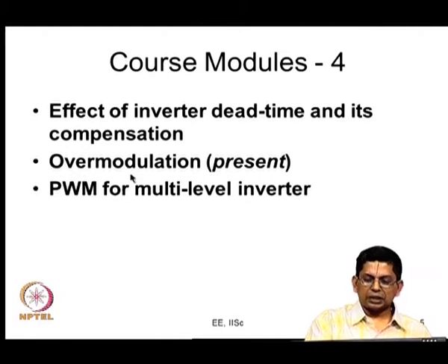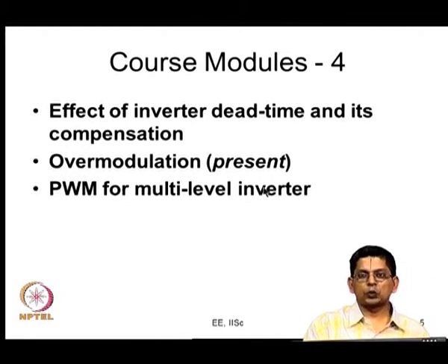Today's and the next lectures would exclusively focus on overmodulation. Today's lecture would focus on overmodulation for triangle comparison based PWM. We try to get an understanding of that problem, and in the next class we would do some space vector algorithms for overmodulation and so on. And then the last one would be PWM for multi-level inverter. All that we have been able to study for the 2-level inverter, we should be able to extend to the 3-level inverter, and we will do some triangle comparison based PWM and some space vector based PWM, their analysis for multi-level inverter.